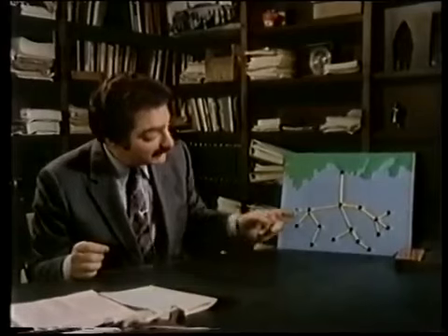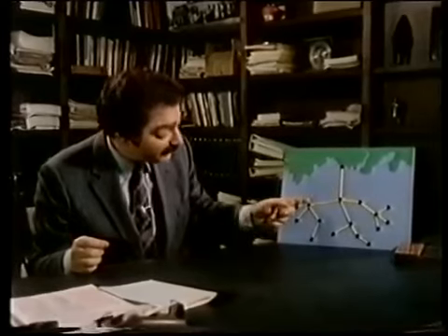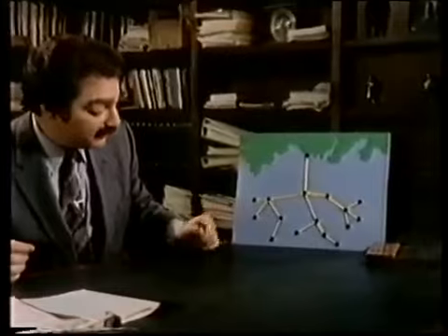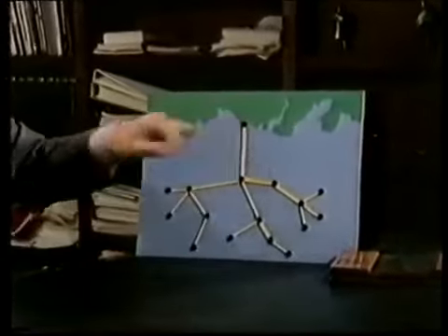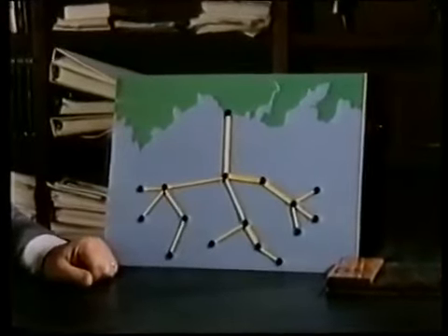The problem breaks up into two fundamentally different problems. The first one is, suppose I had this network. Suppose, for instance, I knew this was a network I was going to build, this exact tree structure. First problem would be to determine the costs and associated diameters of each of the pipes within the network. To do that, I would have to design the network in such a way that I met the crucial variable, that is the pressure constraints at the gas fields and at the onshore collection point.